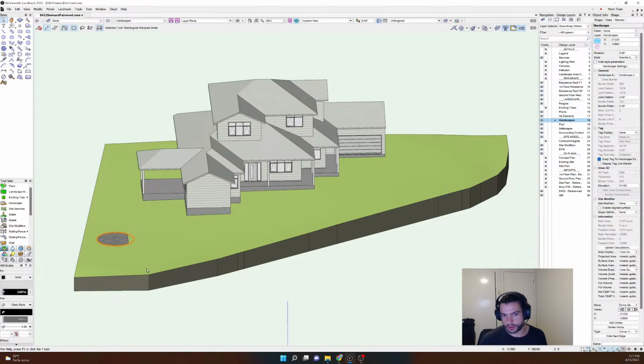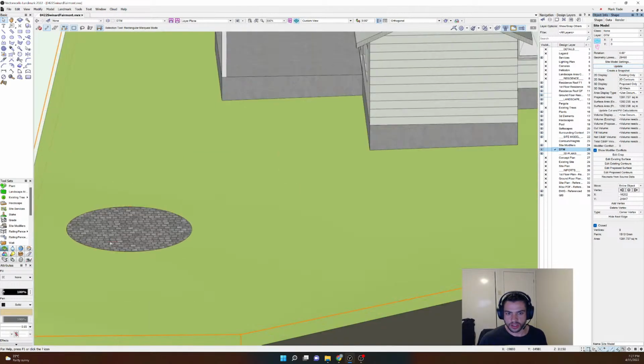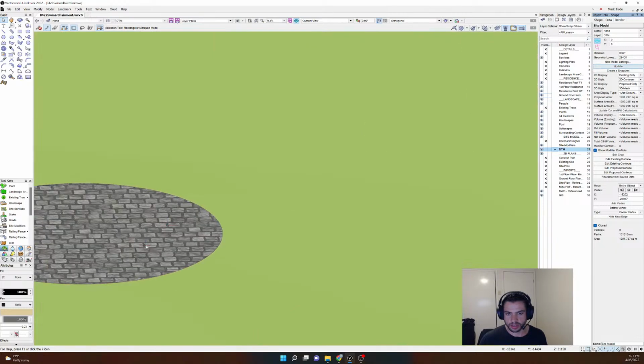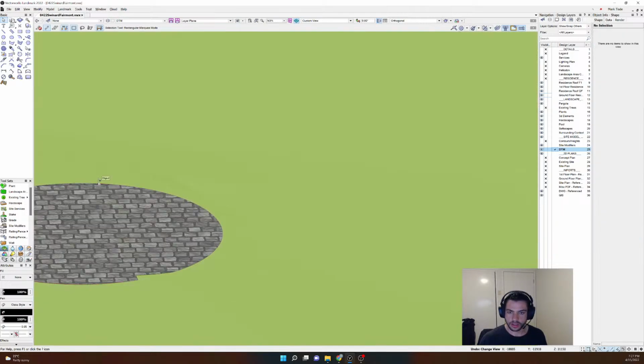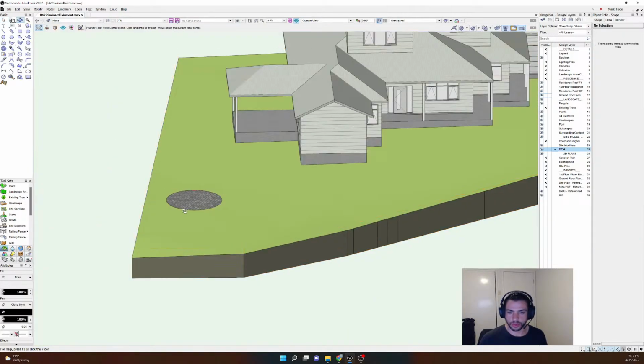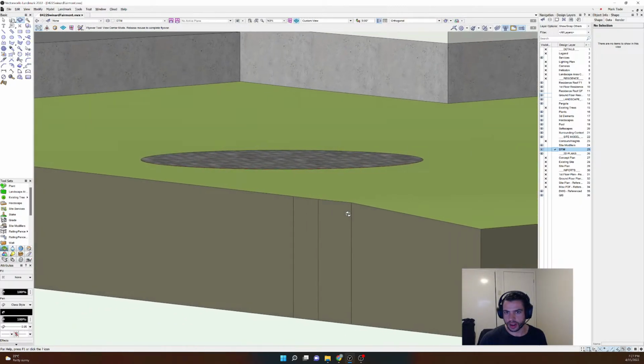We want to do that because if I now change the site, in the site modifier tab of the hardscape objects, I go to site modifiers, modifier at the top, and select that, and then I go back to my site model layer, which is my digital terrain model or DTM layer. I then update. You can see how that has actually pulled the site model to that hardscape.